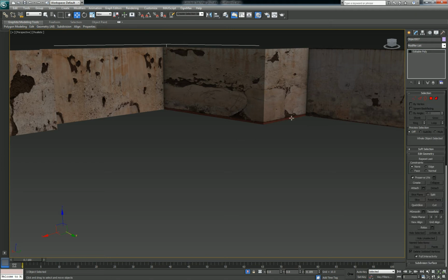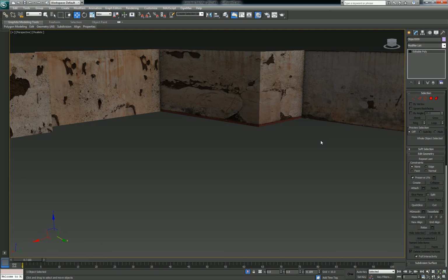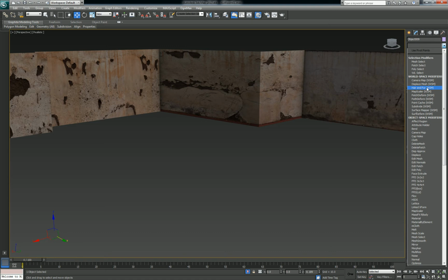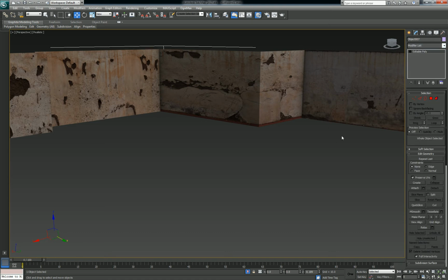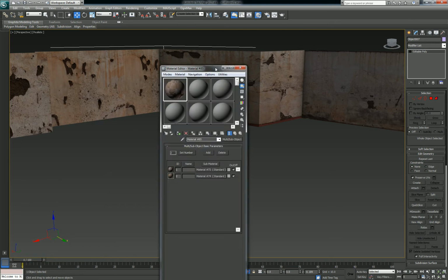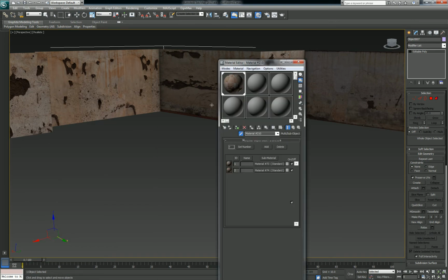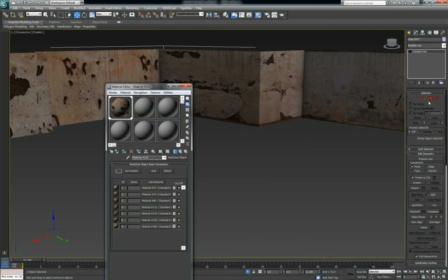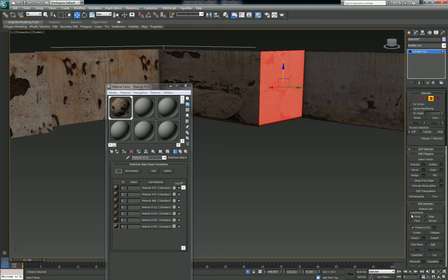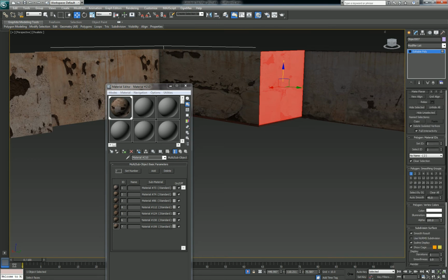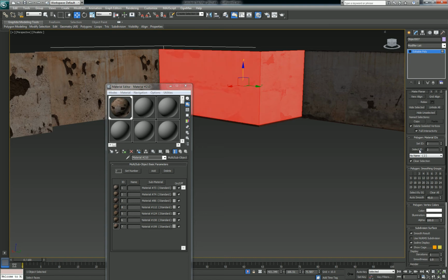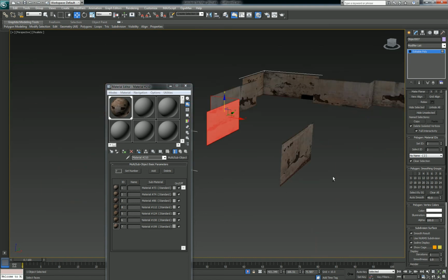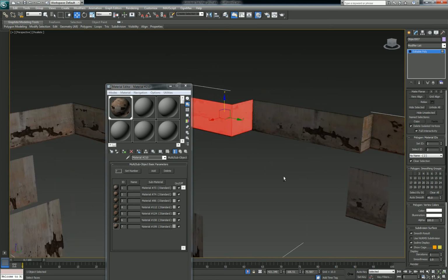Okay, and I'm going to select that bottom edge. I hope I got it. Yes, I do. I'm going to see if I can figure out which material ID I want by using my eyedropper tool and selecting it. I know this has that nice little bottom edge there. If I select that and use my select by ID tool, let's take a look around. That happens to be the only one with that ID on it.